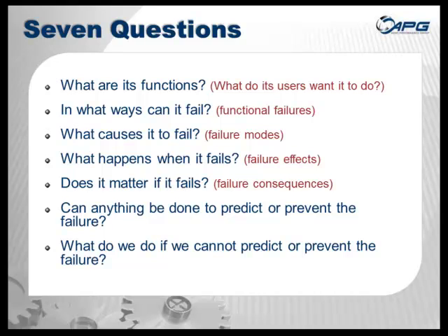The next piece deals directly with decision making and appropriate tasks to support the decision. The first step, though, is to actually understand how a failure mode matters. It's categorized into one of 4 categories: hidden, safety and environment, operational and non-operational. And when failure effects are written very well, it's quite easy to interpret what the direct impact is to the asset, the people, the stakeholders of the business. And for each of those categories, the group then attempts to look at a predictive or preventive task to try to manage or mitigate those failure consequences.